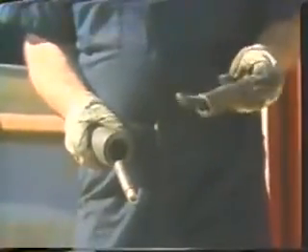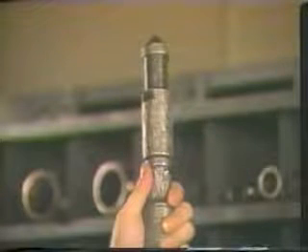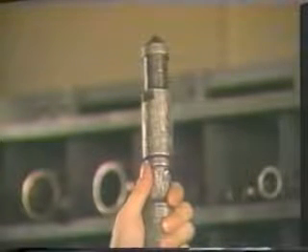With this type, a wedge and a thimble are used to attach the wire line. The wire line is bent around the wedge and pushed back into the thimble. The body of either type of wireline socket is machined with an external fishing neck flange, which allows latching and retrieving the tool string if it should become lost in the well.